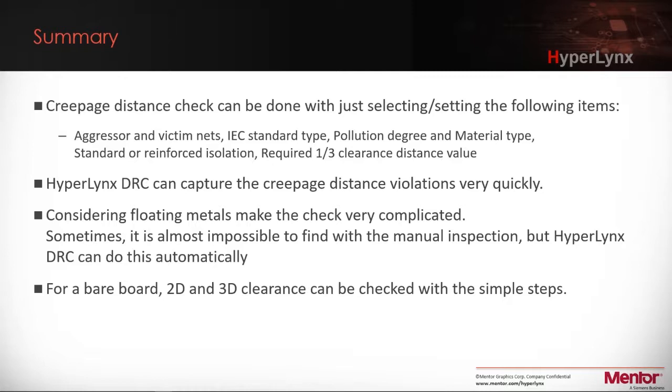We also have not only same layer 2D checks, but we have the 3D clearance checks. We have the multi-layer rules where we're checking the outer layers of the PCB, where we're checking the board edge of the PCB, and we're also checking through a hole or through a cutout in the design. So with these expansion rules, the multi-layer rules, we are covering more safety issues and more use cases for validating a PCB in a safety area today.